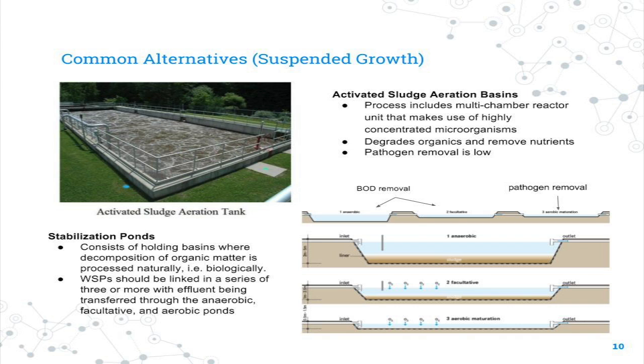This treatment is very good for the removal of organics and suspended solids. For stabilization ponds, the stabilization pond systems operate in 3 stages, with the anaerobic, facultative, and aerobic ponds. The first stage, anaerobic ponds, achieve a high volumetric rate of removal by decomposition.